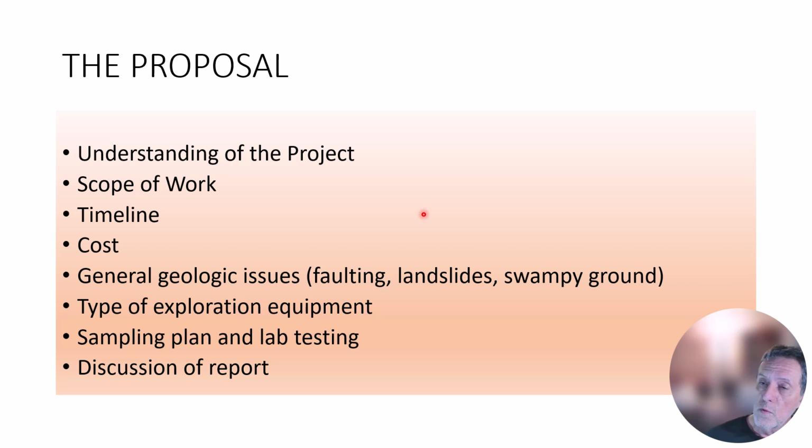So once we do the reconnaissance work and a very preliminary desk study, the engineering geologists and geotechnical engineers will put together a proposal for the client to review and either accept or reject. It has to include an understanding of the project, the scope of work for the investigation, how long it's going to take and how soon it can be started, the cost of the investigation, a discussion, generally speaking, of geologic issues. You don't want to get too detailed before you actually explore the site, but you may have some knowledge preliminary to the investigation of faulting, landslides, etc.